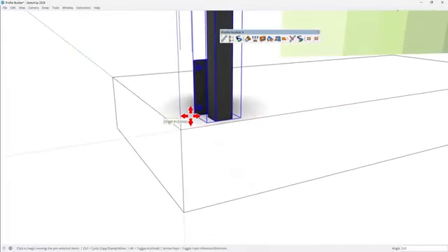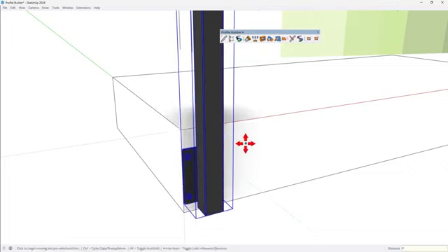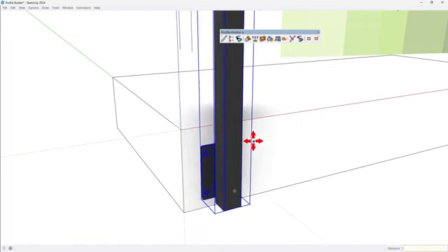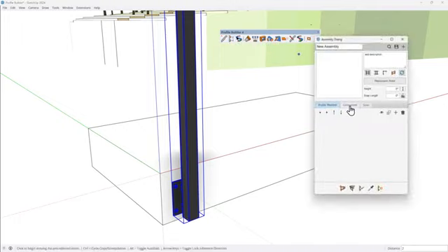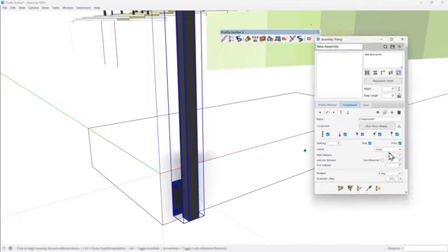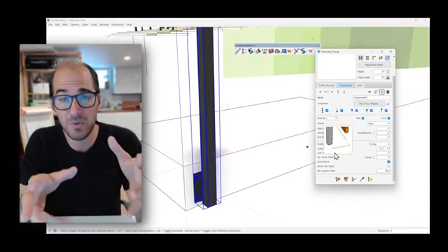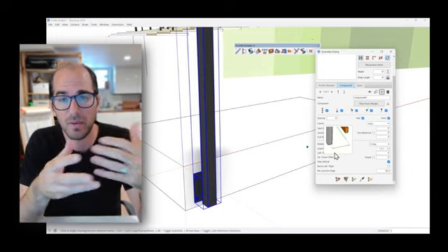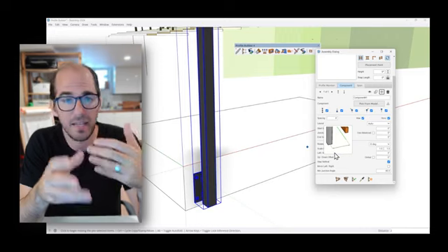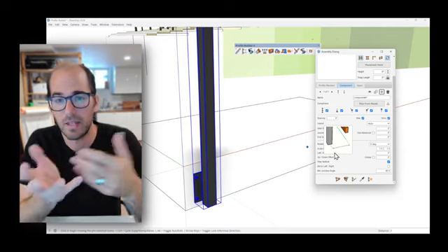And then I'm going to position it relative to where I want it in place here. So I'm going to bring it down 8 inches and I'll bring it over maybe 1 inch or 2 inches. The benefit of auto assemblies is you don't have to build and understand all the spacing requirements and setback requirements and up and down offsets, right? This here is what would take a lot of time. So when I've created setbacks, I usually mess up a lot of what I need to put here. And I'm just kind of guessing, right? So this takes the guesswork out. You're defining it in SketchUp versus in the dialog.